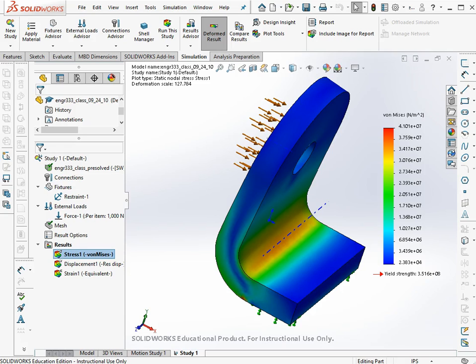So you break apart into multiple elements. The corners of those elements are called nodes, and for the most part, we're only going to be able to get data at particular nodes. So with that in mind, it's helpful to see how this has been broken up so that you can see what points you can actually find the results at. So I'm going to show you how to show that meshing on the plots that you have.